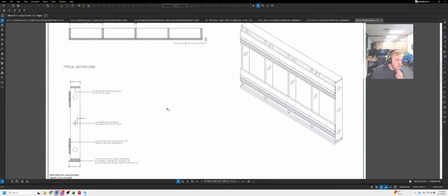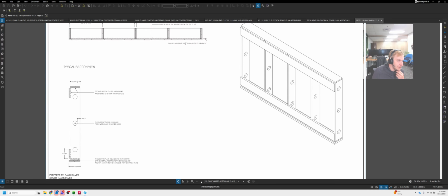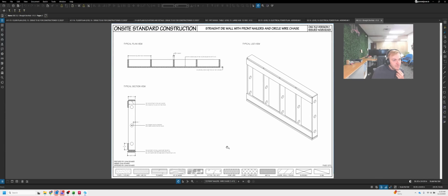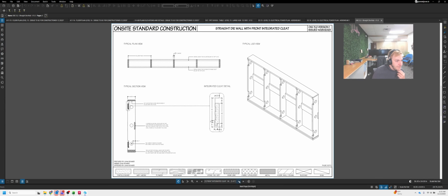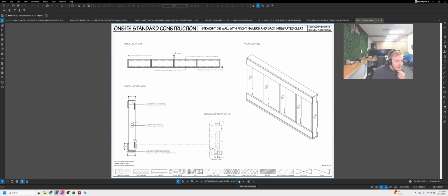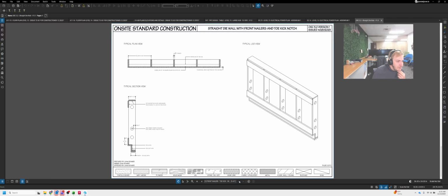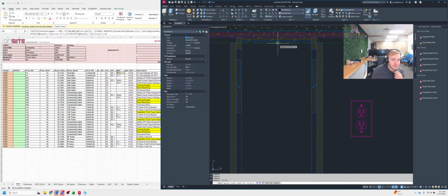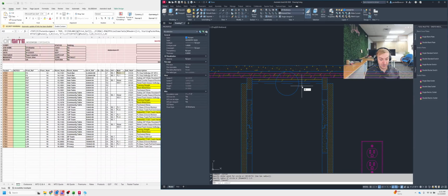Let me just make sure that there's not a specific minimum for the hole on here as well. I'm going to scan through this real quick and make sure it's not noted anywhere. Okay, cool. So what I would like to do in this case is probably make this a 1.5 inch radius, so a 3 inch diameter hole. That gives us plenty of room here. We're not going anywhere close to the edge of that rib. We still have 3 1/16 inches before we hit the edge of that rib, which is fine.